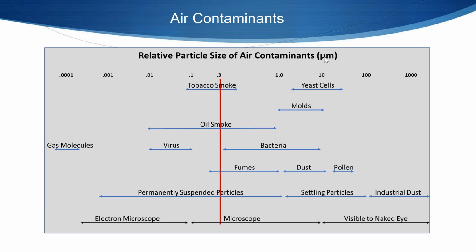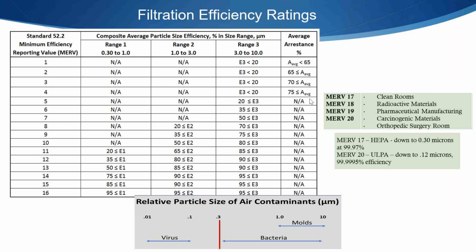In the visible-to-the-naked-eye realm, we've got our dust, pollens, molds, and yeast cells. Virtually any filter in a commercial setting, your MERV 7 and MERV 8 filters, are pretty effective at eliminating those larger particles.